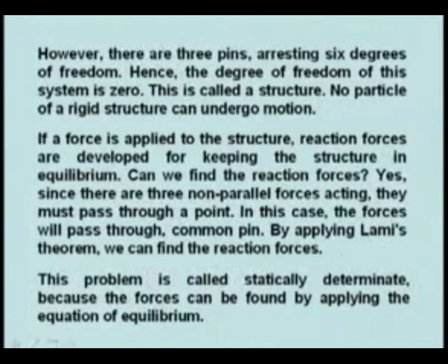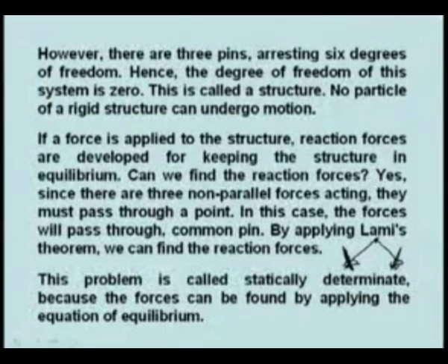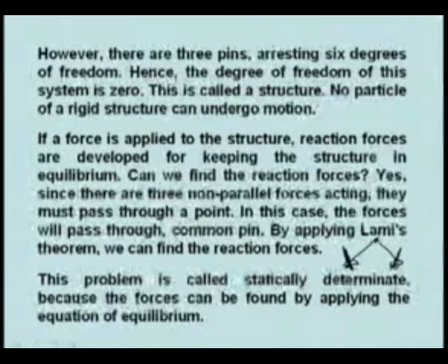Now, if we have a simple structure like this, with this pin joint and another pin, can we find out the reactions? Because these are three non-parallel forces on a body, we can find out these reactions. There may be some reaction here, and there may be a reaction here, so we can find out the reaction forces.